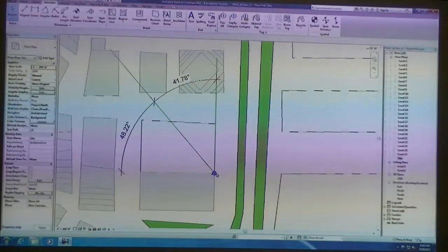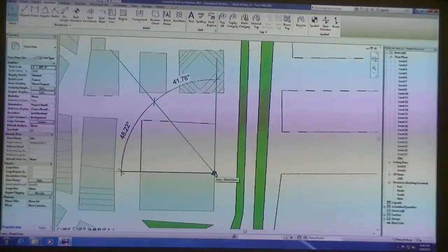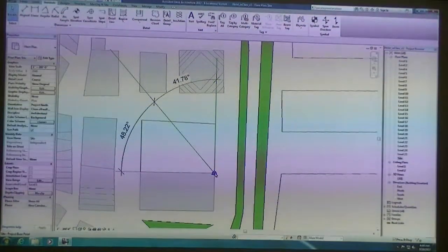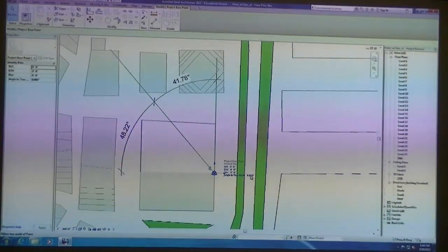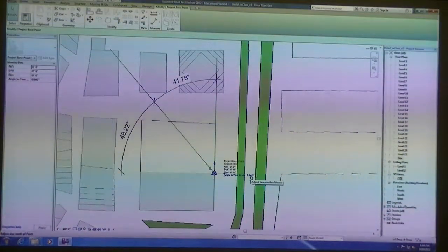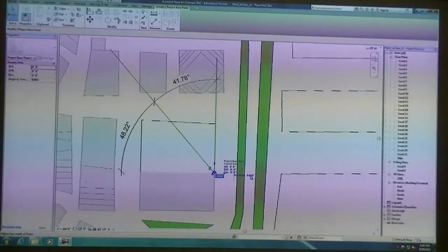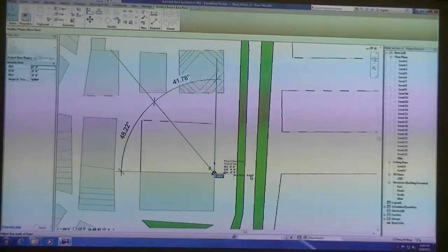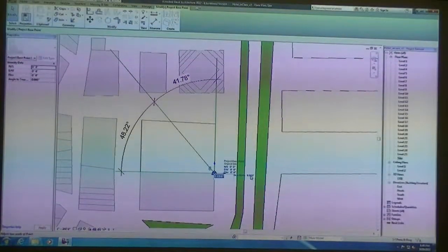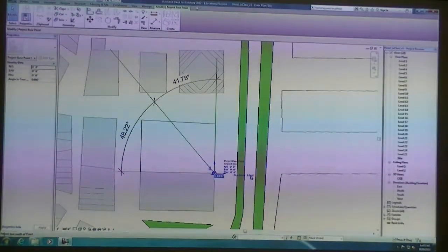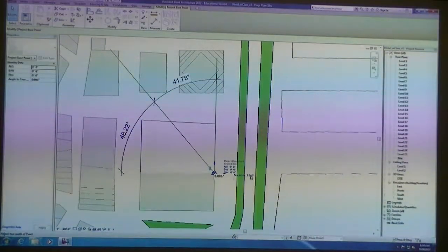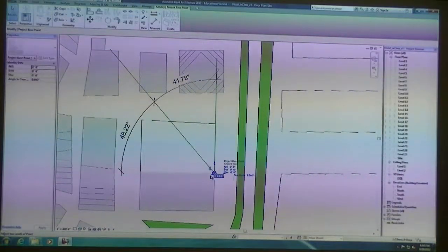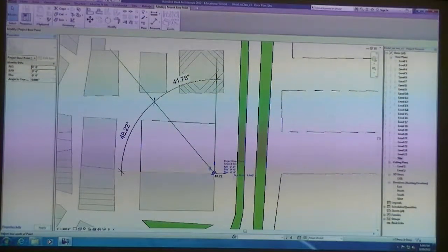So I'm going to tab over. Let's see if we get this right. Tab over until I can get my site project base point to load up. And then I can click on the blue text called angle to true north. And we can type in, well, I guess actually we should type in 48.22, because if we rotate it at 48.22... My number lock's not on. And then I'm going to type in under the angle to true north 48.22.